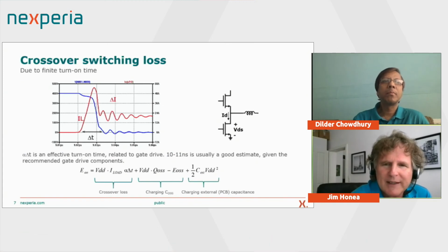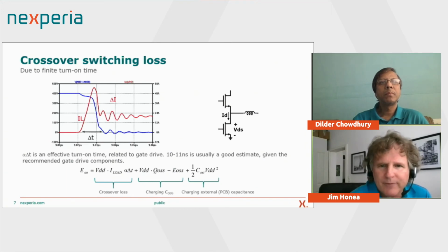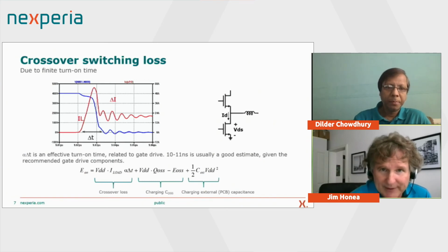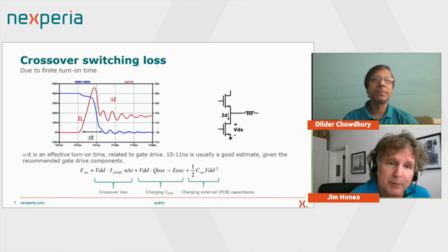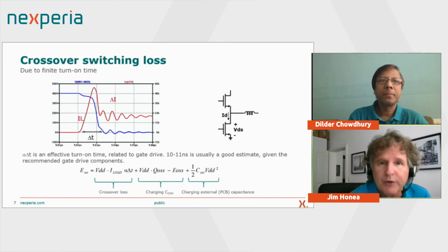I would say with our demonstrators, we specifically avoid that simply because parasitic inductance complicates stability. And with a high-speed transistor, keeping the switching stable is critical, right? We don't want to create oscillators. And for that reason, I would say our recommendation is to avoid parasitic inductance and not try to minimize switching loss by adding parasitic inductance. But in principle, it would do that.